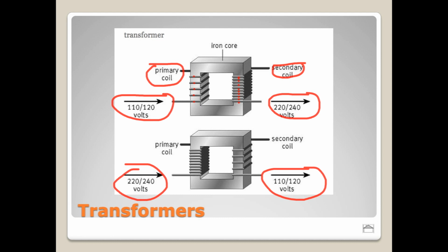This is really helpful if you're trying to run a piece of American equipment over in Europe, because remember, European voltages range between 220 and 240, and American voltage is 120. Notice this diagram also lists 110 as an option. That's just to indicate that sometimes we actually have as low as 110 because of voltage drop from the service entrance on the building.